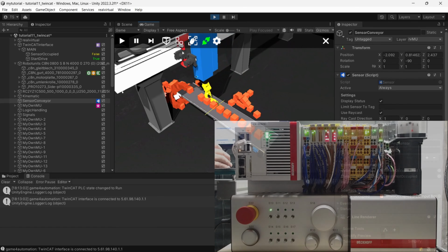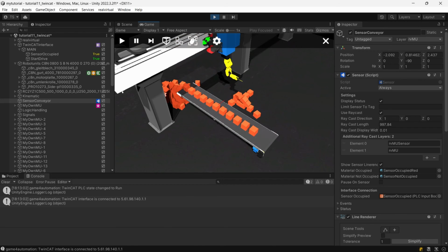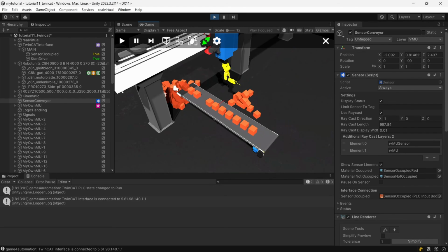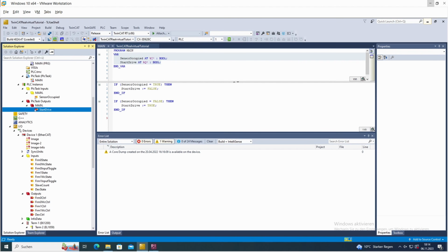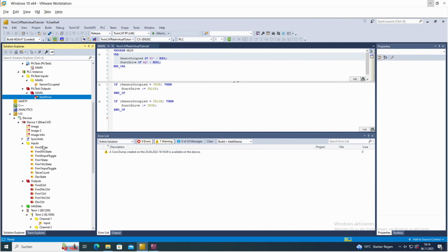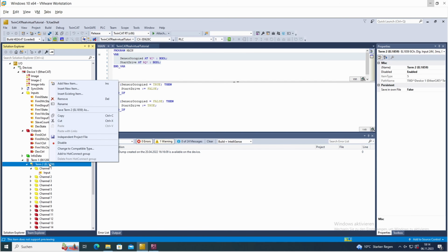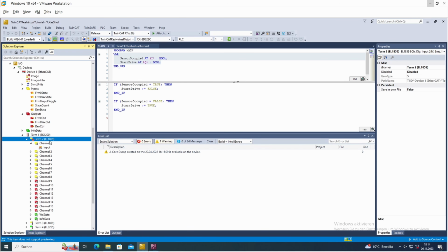So what you should make sure, if you're doing a virtual commissioning and if you are having real hardware I/Os connected, is that your I/O devices, in this case, for example, let's check our device here, this terminal, this first module should be disabled.